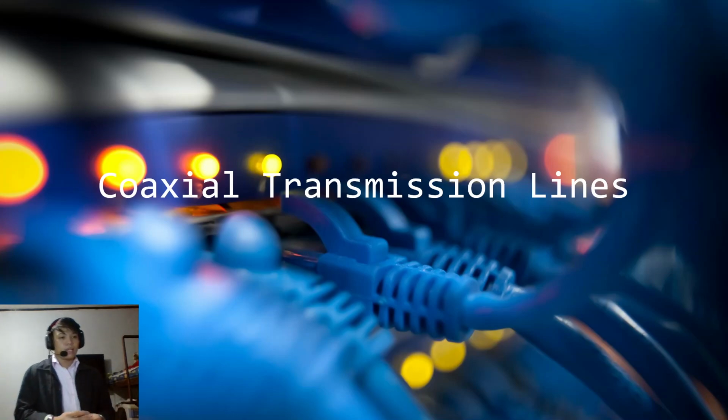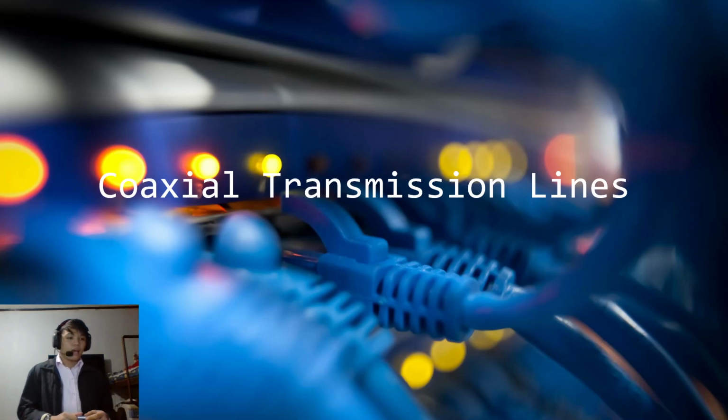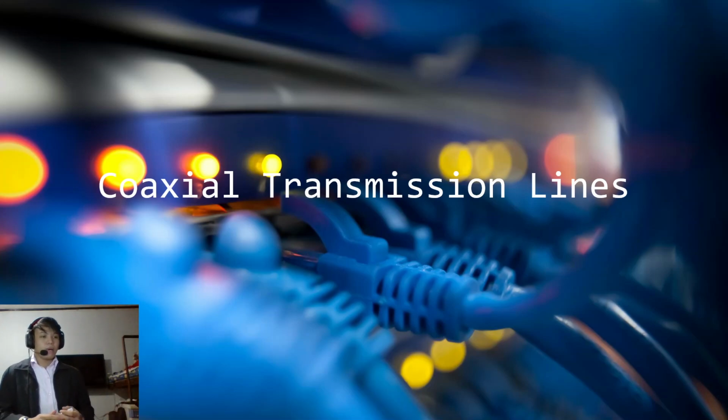There are many types of transmission lines. The first one is the differential or balanced line, where neither conductor is grounded. Two-wire open lines or parallel lines have uses such as power lines, rural telephone lines, and telegraph lines. This type of line has high radiation losses and is subject to noise pickup. Twin lead has parallel lines. It is most often used to connect televisions to their antennas.